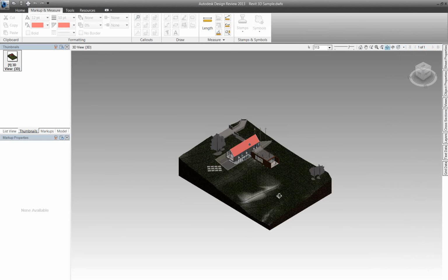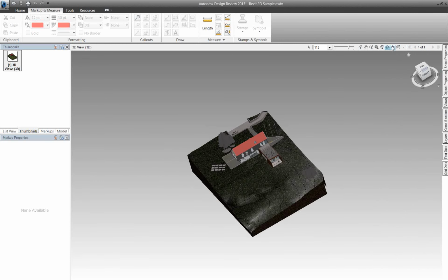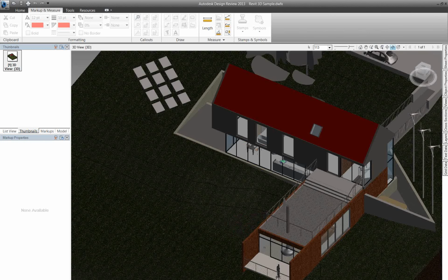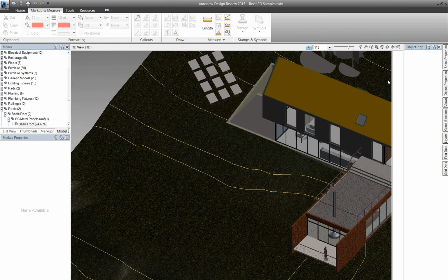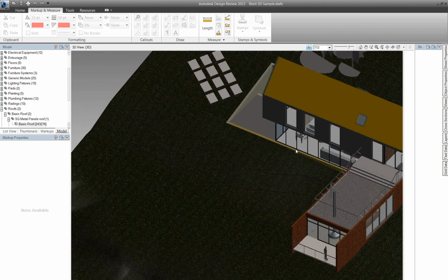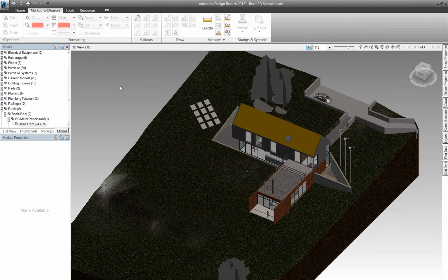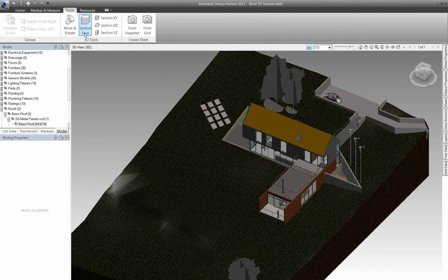Yeah, so we have some navigation tools. We have a constrained orbit tool here. You can actually select items in the Revit model, the 3D model, and view different kinds of properties over here. So there's more stuff we can use here. There are actually 3D measuring tools we can use. There are section tools. If you go to the Tools tab, you see we can actually create sections on the 3D Tools panel over here. So, you know, that might actually be something maybe we do a special webinar solely devoted to. Probably would be a good one. DWF, yeah.